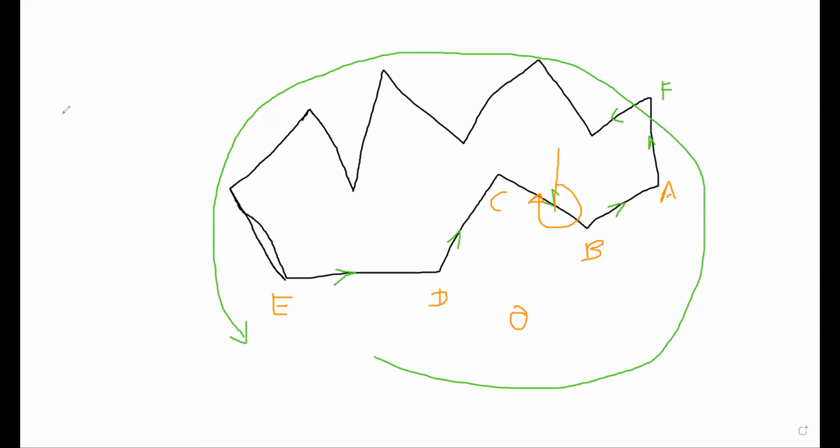So there are three conditions. One is anti-clockwise movement. Then start with the line with the whole circle bearing in the forward direction. In this case, you have to start with CB. After CB, you are moving to the BA line. This is our movement: CB, BA. If you have marked everything in anti-clockwise direction, it is very easy.